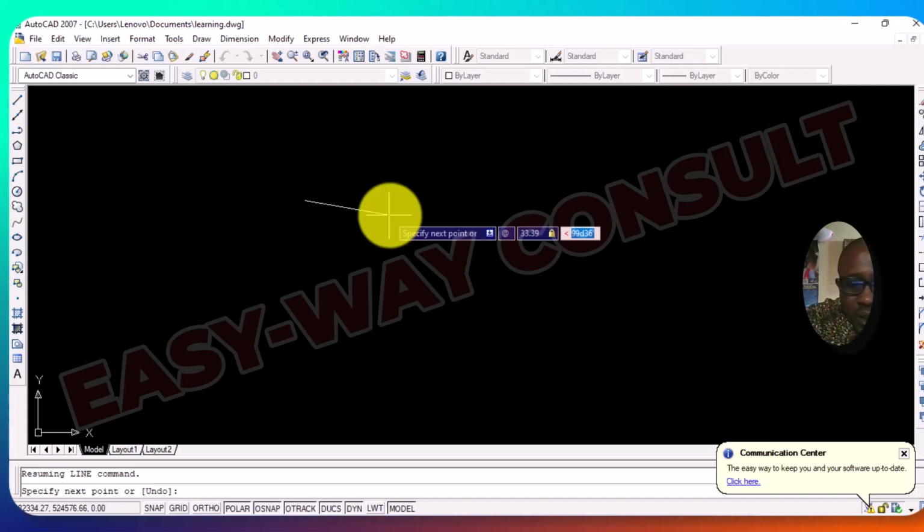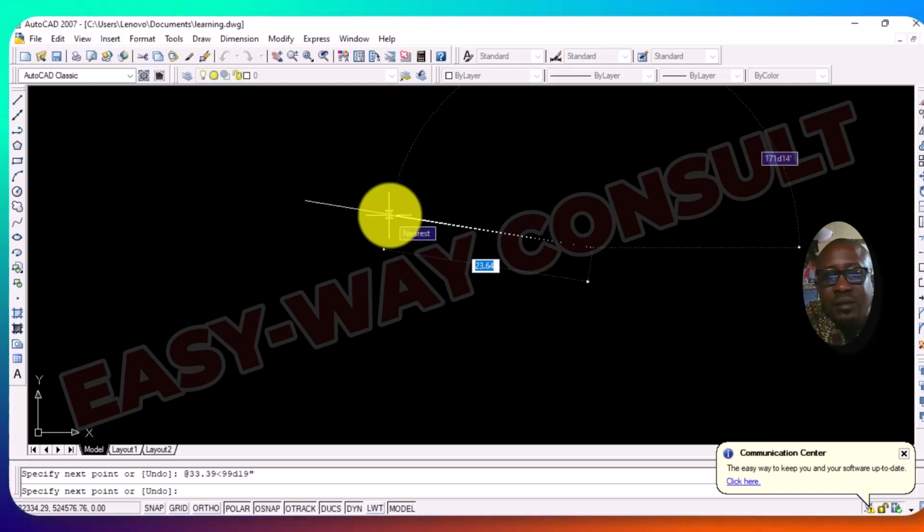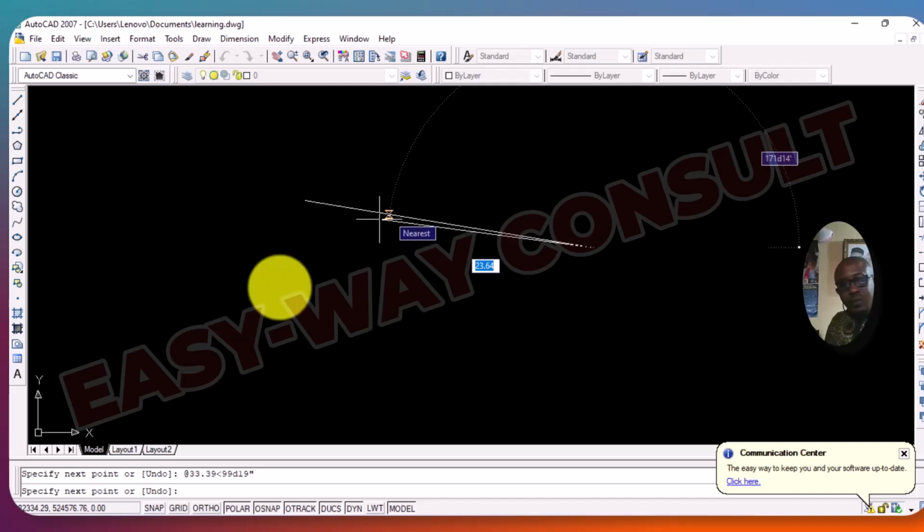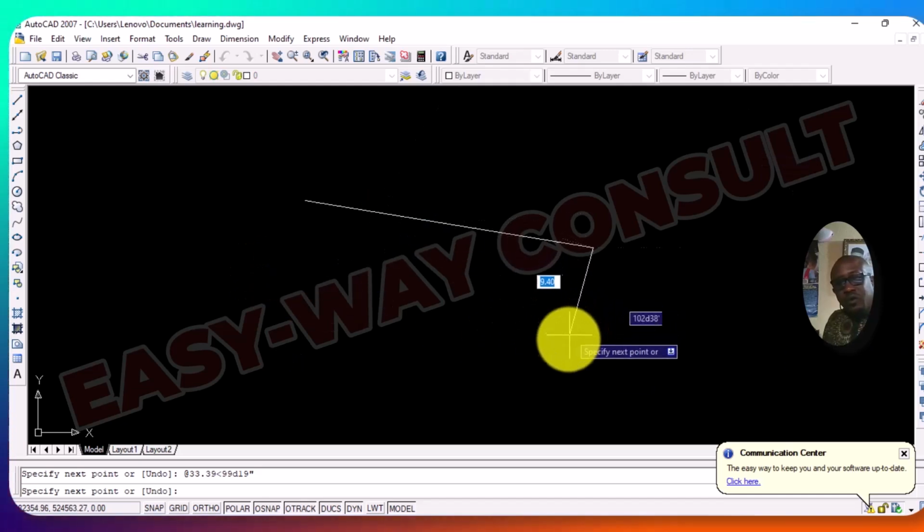Then you type 99, D, the small letter D, then your 19 minutes. Then you hold shift and type the sign for minute, and you say enter. You have gotten your first one.